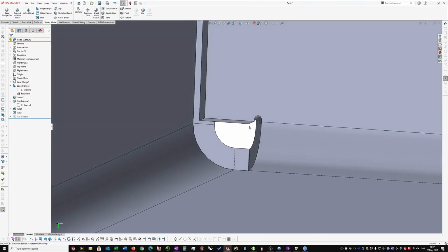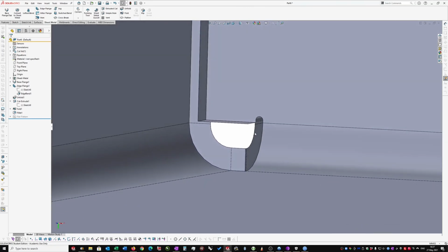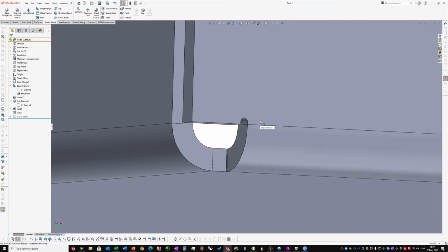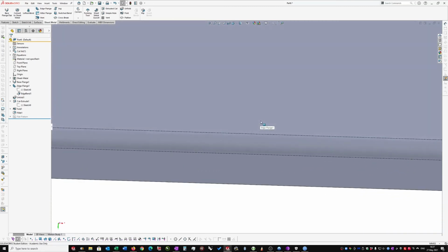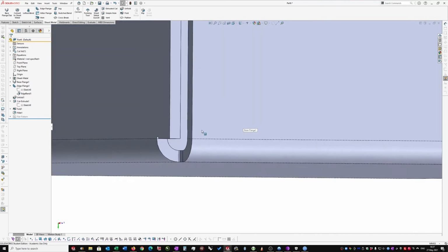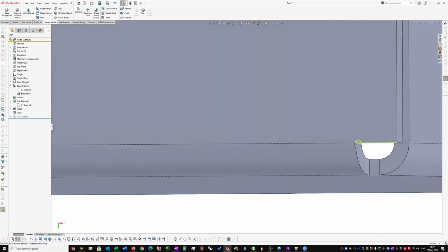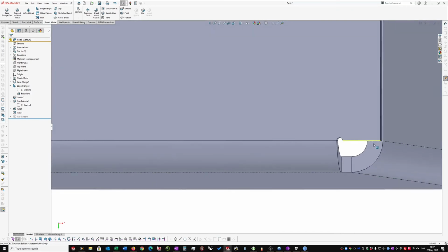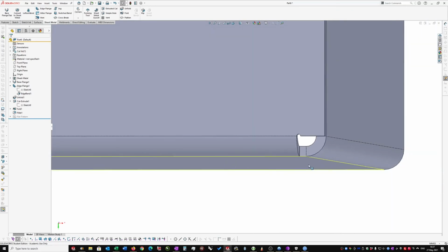Otherwise, Solidworks interprets that as not a legitimate cut if this cut is at the level of the extremes of that bend or below it. So on that end, and this end will also work, maybe not in the same way, but will still give us some sort of result. Okay, so it's almost the same, it's pretty good. So either of those two solutions would work.